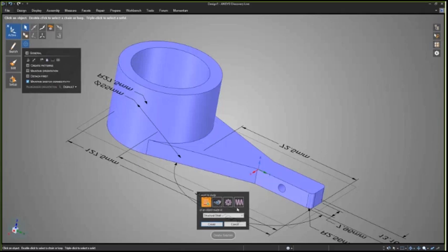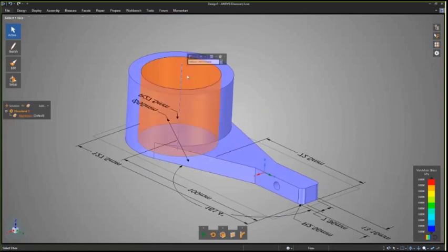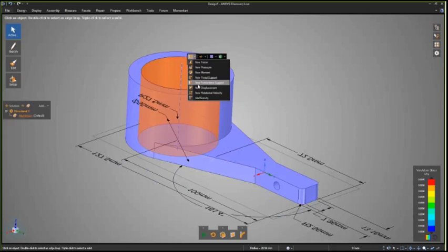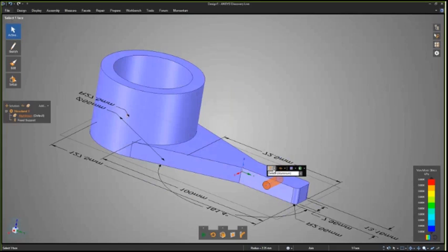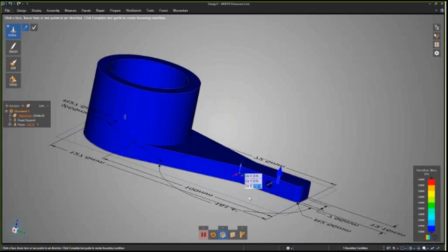I would say that every single point release of Discovery Live has had phenomenally new functionality. So you will get something new in every release. But let's say we're going ahead and set up a structural simulation here. Everything is very hands-on and interactive. If this space here is going to be fixed, I can just select it and look through these different types of inputs or boundary conditions that I can apply. For example, a fixed support. Over on this hole, maybe that's where a load is going to be applied. So, it could be a moment, a number of other things, a pressure, but here we're going to do a force. And I can go ahead and look at that force. And I happen to want this to be in Z. And so we'll do 100 up in Z.